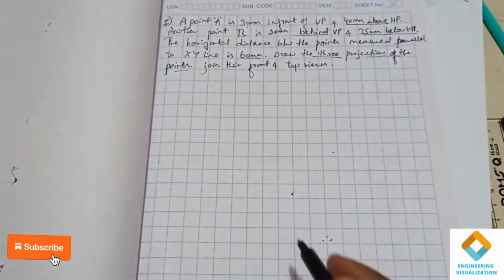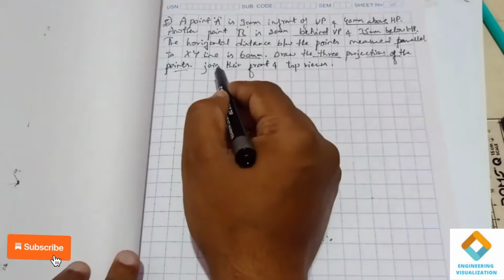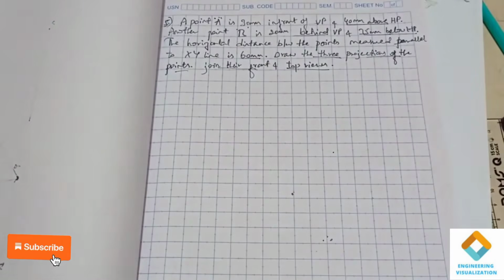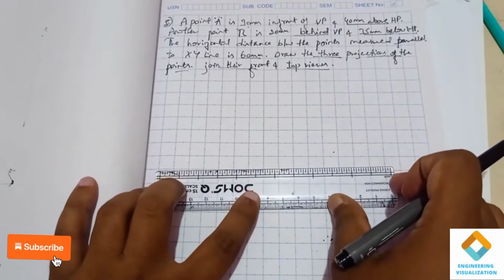Three projections of the points means here top view, front view and side view. Join their front views and top views. So we have to join both their top views and front views. Now first I am going to draw an XY line here.